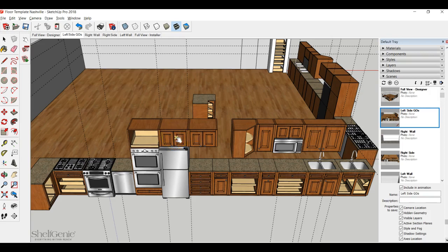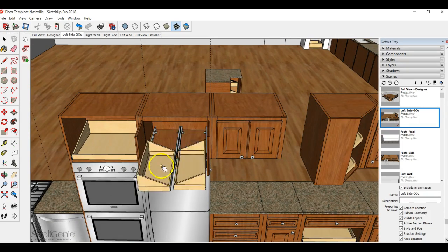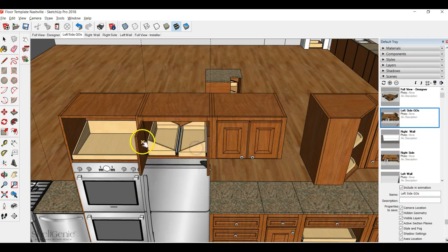There are two types of cabinet depths on the upper cabinets normally that we see. One is refrigerator depth, which is comparable to what we have with a double oven, and the others are more along the 12-inch or 300 millimeter depth, and that's what all of these cabinets are built to. So if I zoom in also, one of the things I did is built it so that we can have some common type solutions. This is going to be a great solution there too.